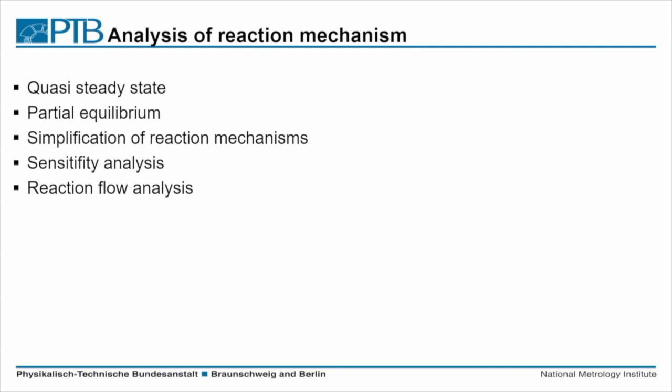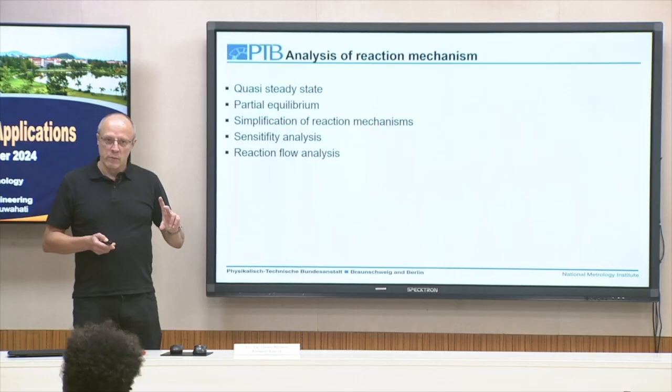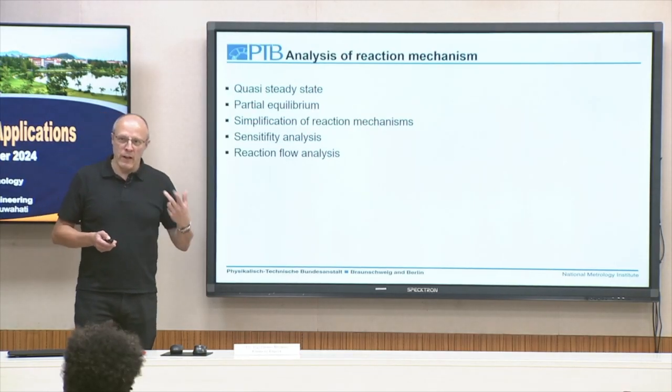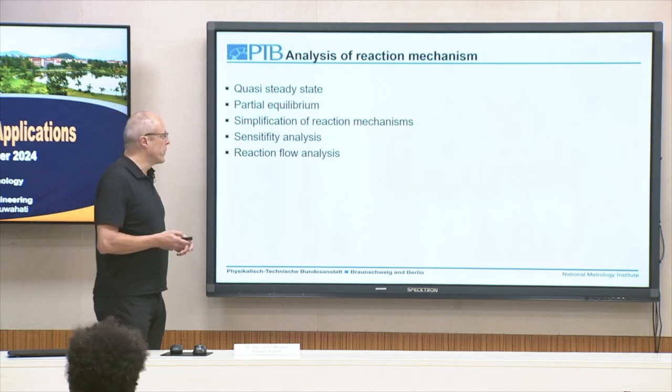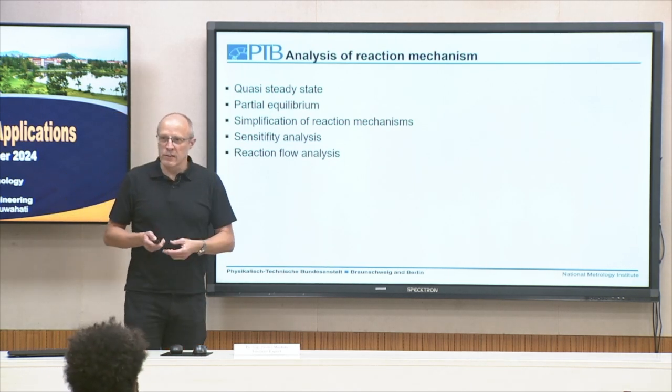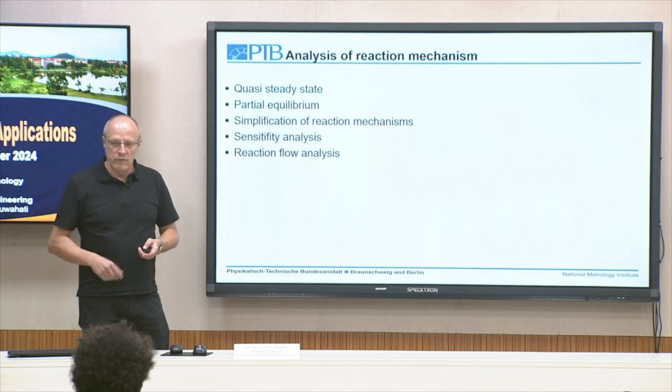Again, we have hundreds of equations, thousands of species, but depending on the problem we are interested in, so is it a laminar flame or is it an ignition event at a specific temperature, is it a lean flame, is it a rich flame, often only very few reactions are important to know precisely, because they are dominating the chemistry, and the rest of the parameters we need just to know very roughly.